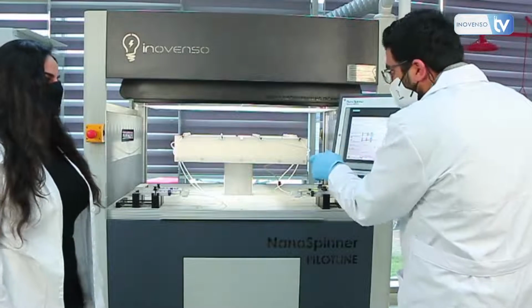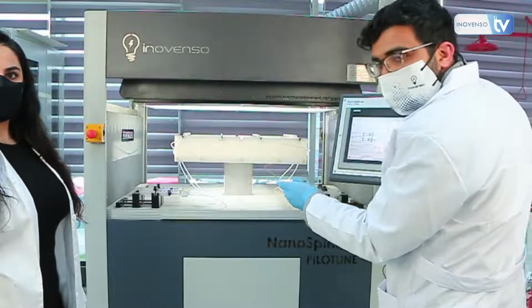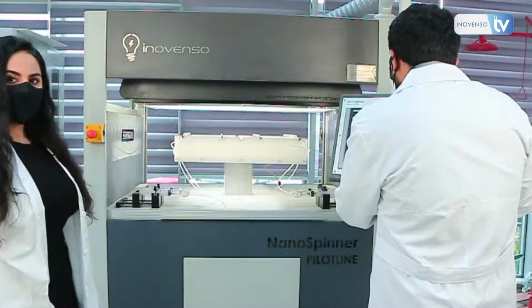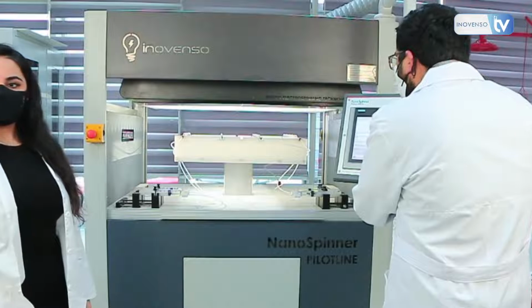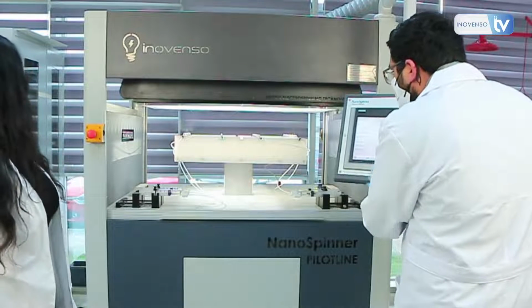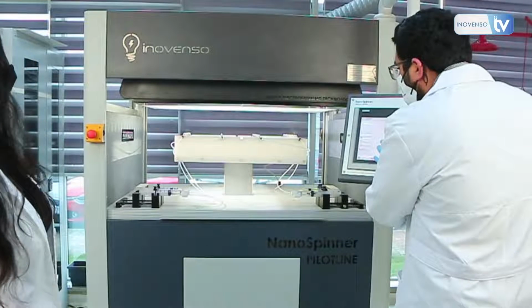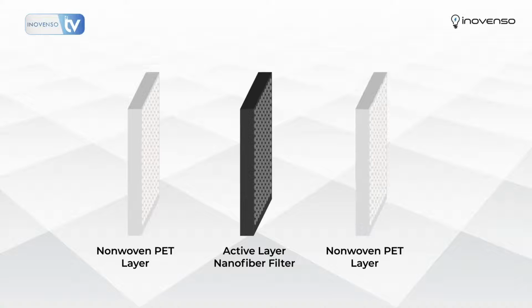So now the syringe pumps are active. You can't see it as much because we're using a very fine meter. So now we're going to put in the high voltage. Okay, now our electrospinning has started. You can see the jets being formed. I'm setting the distance to be 140 at nozzle mode, and I'm going to start the roll-to-roll collector system.